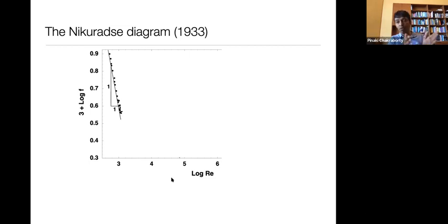Okay, so when the Reynolds number is low, the flow is laminar. At least to experimental precision, all of his data collapse onto a single curve. So that's the curve where we are going up to Reynolds number approximately 2000. And this is the laminar regime, and friction factor F goes as inverse of Reynolds number. So this is something we can predict exactly.